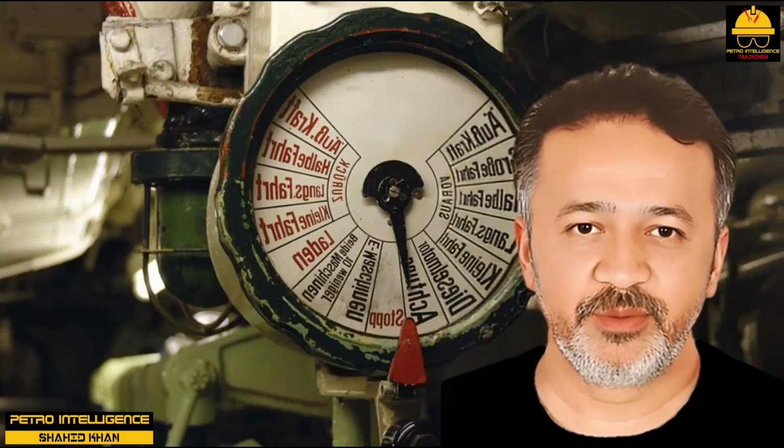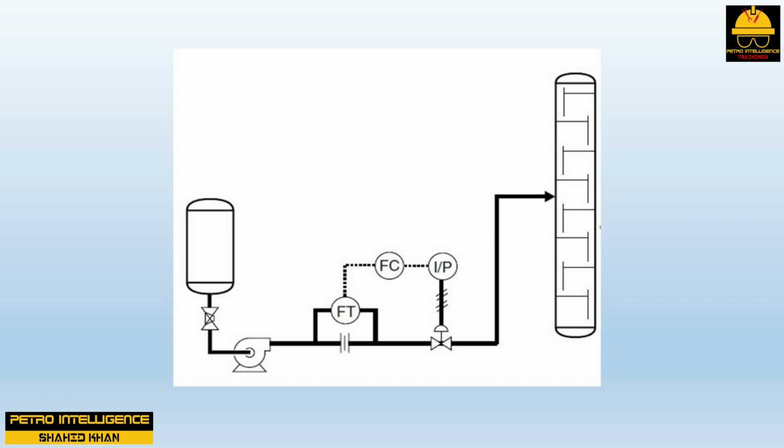Flow control loop. Flow control loops as shown in picture are typically designed so a measurement of the flow rate is taken first and then the flow is interrupted or controlled downstream. Flow control loops start at the primary element, which could be an orifice plate, venturi tube, flow nozzle, nutating disc, oval gear, or turbine meter. The most common primary element is the orifice plate.